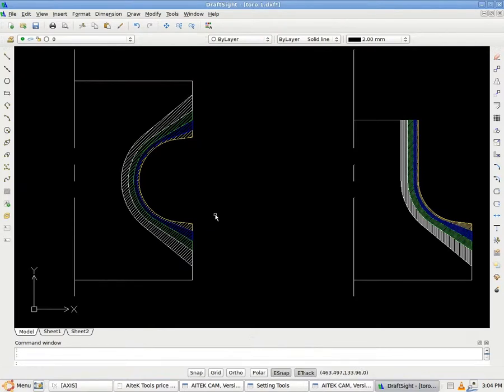Like for removal, each tool must get closer to the bottom of the stone. You can look at each tool position, and one by one set them closer to the bottom. Or you can check the position where each tool touches the stone bottom. And starting from the last diamond tool, for each previous tool you remove 0.1 from the Z offset. In this way each tool will be higher, and the lines left by each tool will be removed by the next one.